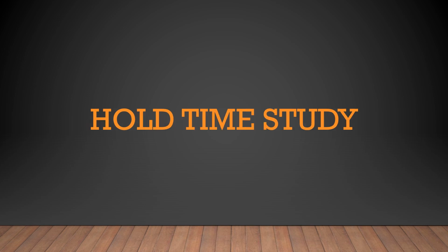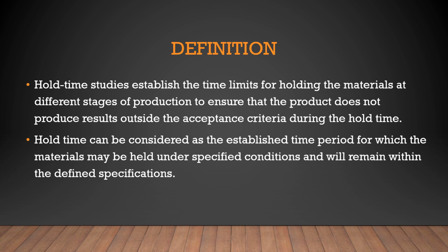Today we will learn about hold time study. Hold time studies establish the time limits for holding the material at different stages of production to ensure that the product does not produce results outside the acceptance criteria during the hold time. Hold time can be considered as the established time period for which the materials may be held under specified conditions and will remain within the defined specifications.